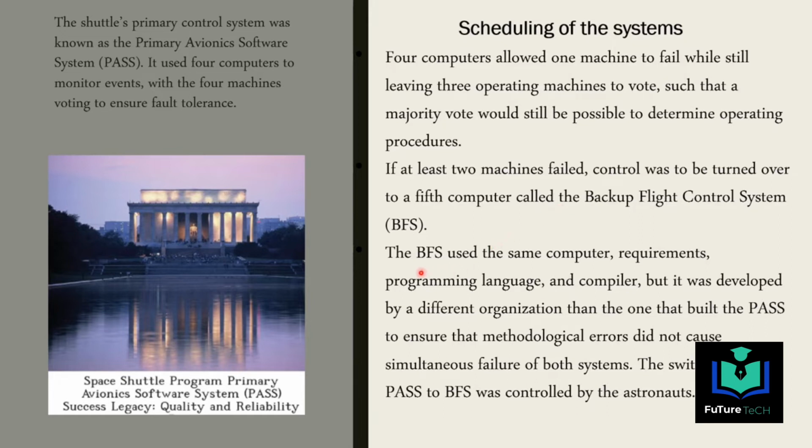So the BFS used the same computer requirements, programming language and compiler, but it was developed by a different organization. Imagine PASS is developed by one organization and BFS by a different organization, to ensure that methodological errors did not cause the simultaneous failure of both systems.